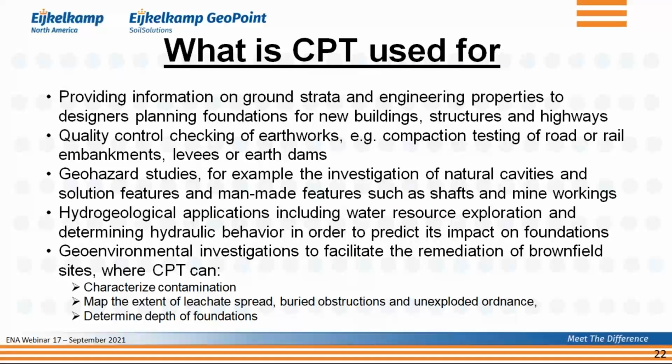And finally, you can use the cone for all kinds of geo-environmental investigations. And that is something that we could talk about at length again, just like we could talk about all the other items at great length. But what you can do is characterize the contamination, but also find the extent of that contamination, as long as you are using enough CPT points to collect data.